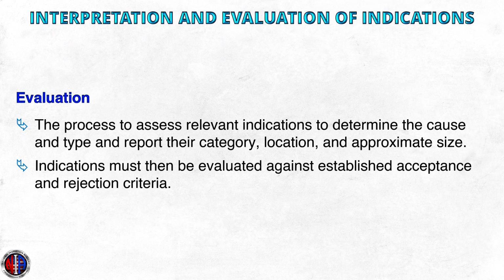Evaluation. Evaluation is the process to assess relevant indications to determine the cause and type and report their category, location, and approximate size. For a more focused evaluation on some indications, use magnification or the double development technique.